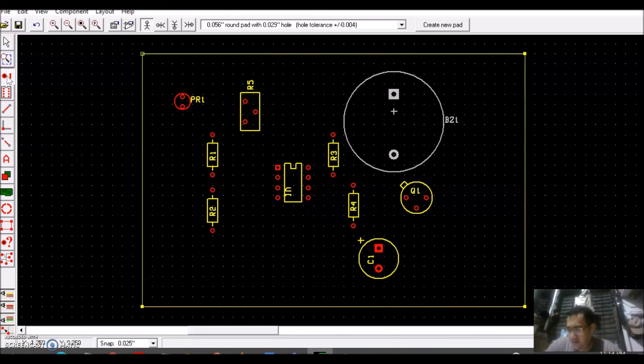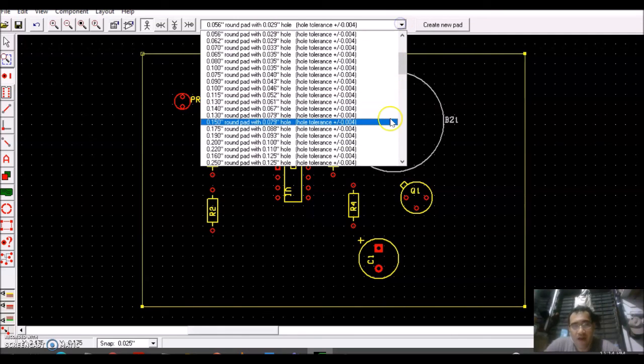This is a good opportunity for us to create a part from scratch. Use the pad tool to place a pad with description 0.150 with 0.079 hole to be the positive battery lead.